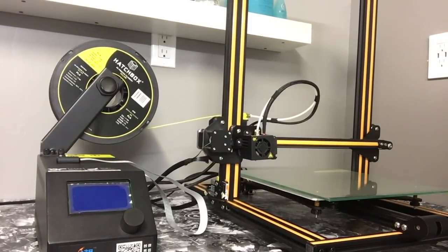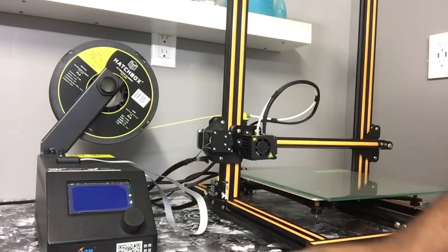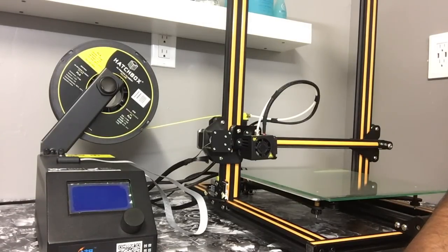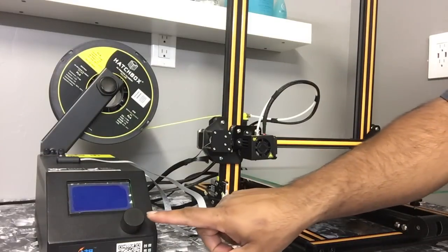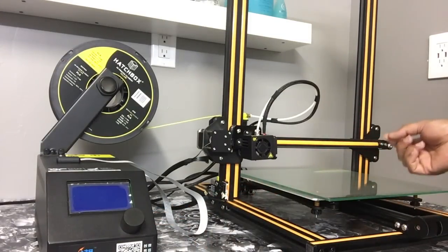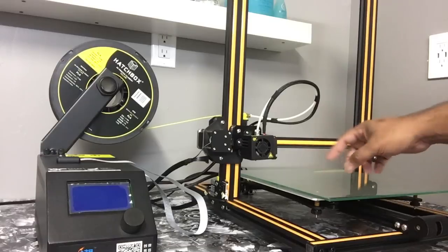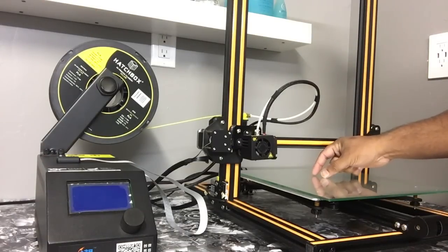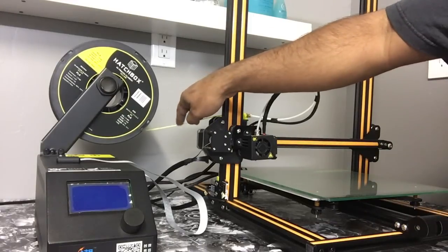Another big question I get is how to change my filament. Well, how do I change my filament before a print? How do I change my filament in the middle of a print? Every printer is different on the menu side, guys. On mine, once you start the printer, there is a tune feature that pops up, and once you click on that, you can go in there and change filament, and then it gives you a warning beep until you change it. Once you're done changing it, if you press this button one time, the printer will start printing again. When you hit change filament, let's say your nozzle's here, it'll just come to the side and wait until you change the filament out.